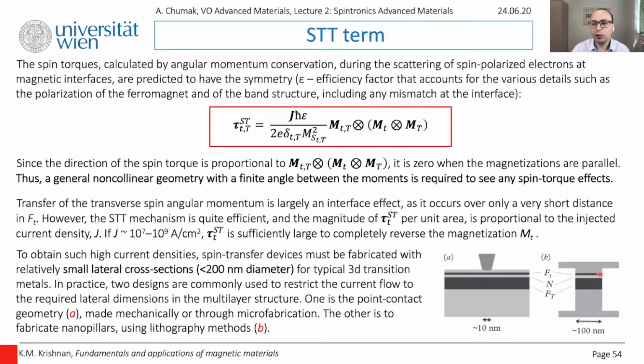So it's not coupled to anything, and you can do it relatively easily. If you want to switch magnetization of some part here, then of course you need to do something with exchange interaction at the edges of this region, which wants to keep your magnetization parallel. So you need 2 orders of magnitude more current in order to break also this exchange interaction to create here domains.